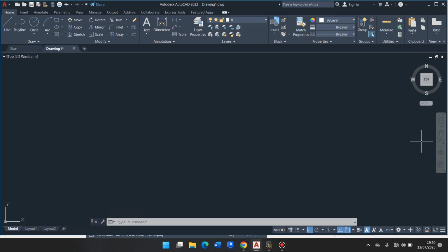Okay, so for now we'll just teach you the basics of layers and what you can use them to do. Now one of the uses of layers is for you to be able to group certain things in your drawing under a name so that you can easily edit all of them. You can make them change colors, change the line weight, or make them disappear altogether.